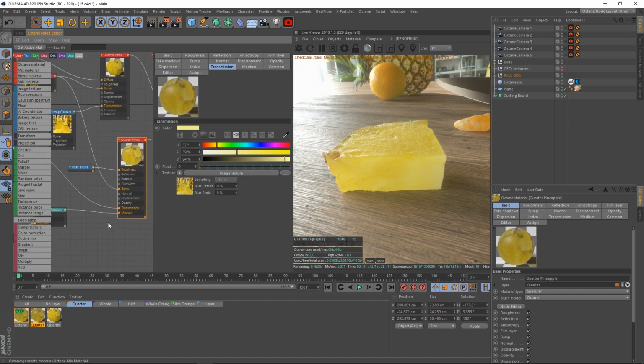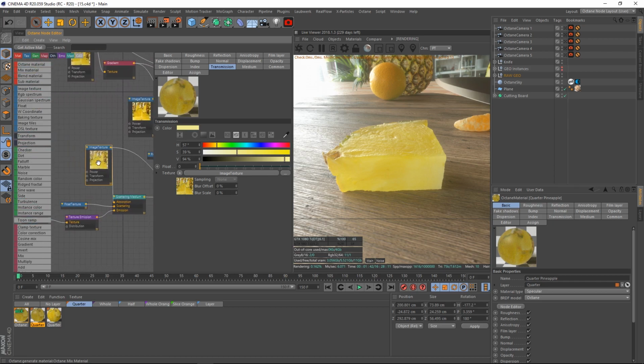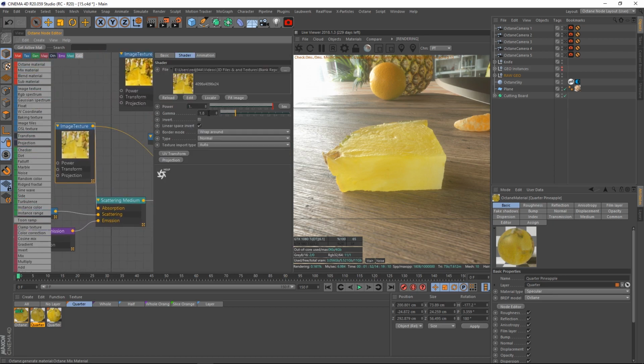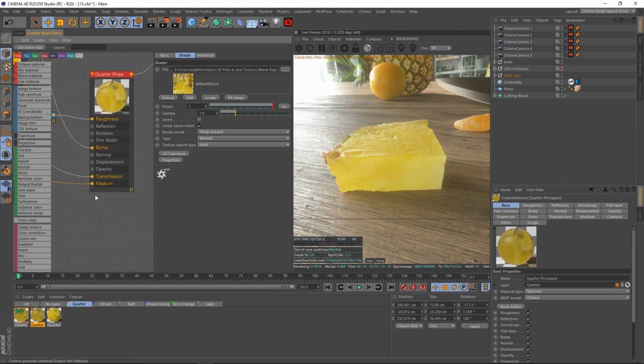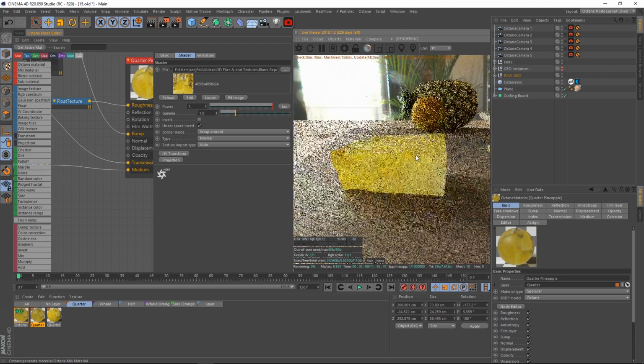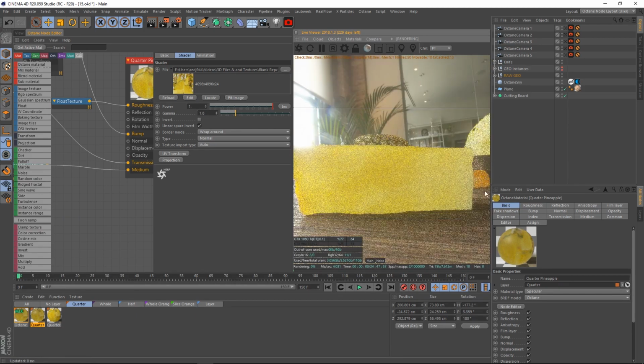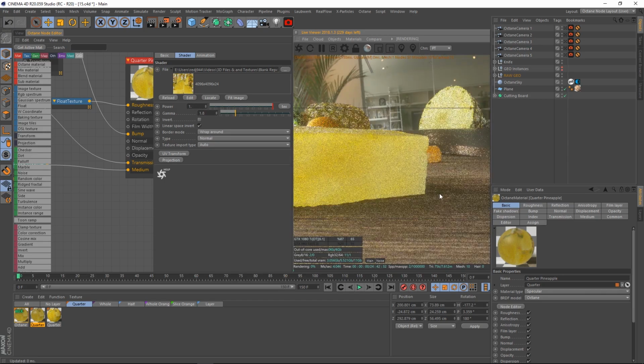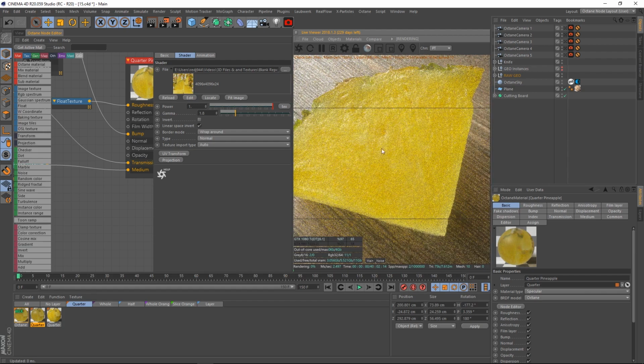And for this is no different. We're just coming up with that based off of this image texture with the gamma pulled down to 1.8 just to brighten it up. So we have our generalized look of the pineapple, and then we can have some absorbed color right down more. So you can see here on the tips of the pineapple, this goes a long way with having the absorption because we're whiter here on the tips. But as we move into the center of the pineapple, it gets more dense, again adding more lifelike realism to it. So the transmission value keeps that constant pineapple color throughout it, but we also absorb down with even a harder, more dense color as we move into the center.